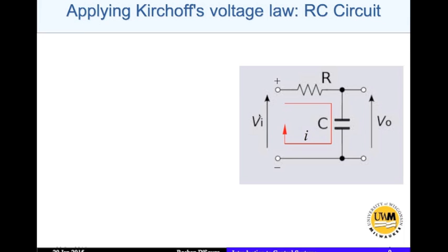So we'll apply Kirchhoff's voltage law. VR plus Vc minus Vi equal to 0. VR is the potential drop across the resistor, Vc is the potential drop across the capacitor, and Vi is the input voltage. And you know why this is negative, because when you march along like that, you hit the negative sign first. Now this is a temporary configuration of this voltage. In this particular configuration, this happens to be plus and this is minus. Vi is in fact an AC signal.